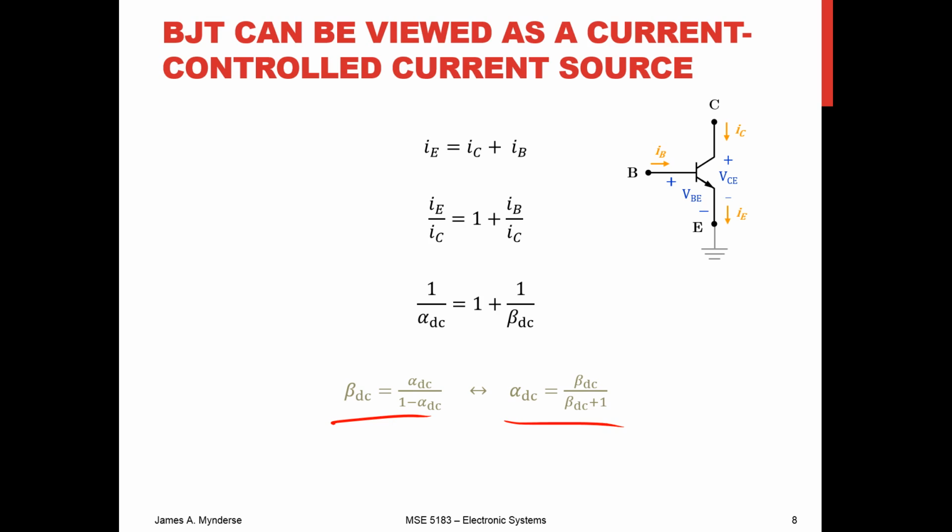And probably what's going to matter most to you is going to be that amplification factor, that's beta, which you're going to see on a spec sheet. So always check your spec sheets. And it might appear as an H or an H sub F or something on the spec sheets. But that's how much current we're getting through the collector by comparison to how much current we put into the base.